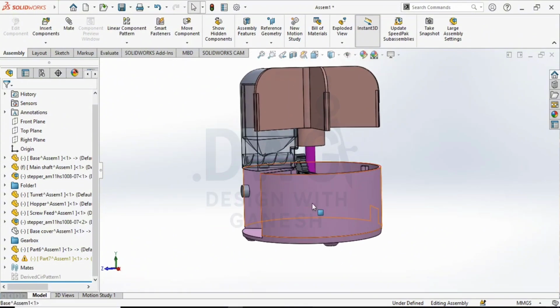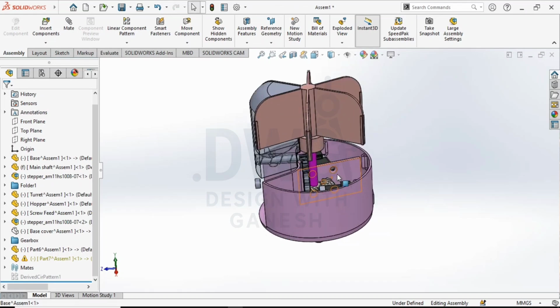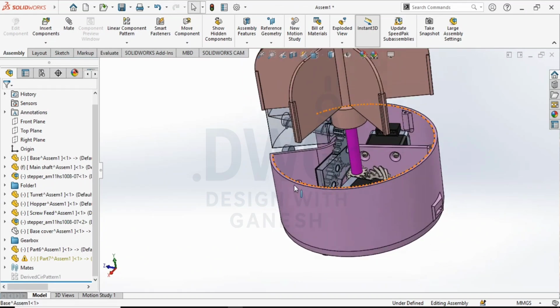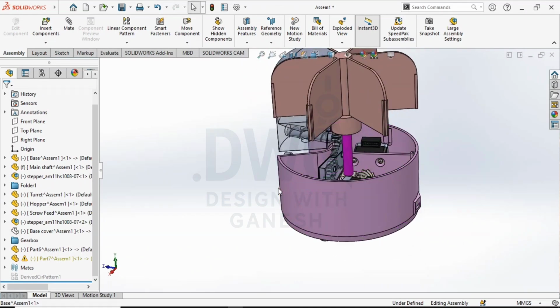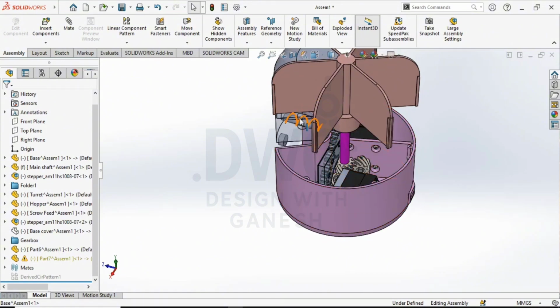If you keep a display and control panel here, through a microcontroller you can command the first motor to rotate and stop at the spice dispenser you need, and the same microcontroller will command this motor to feed this screw feeder.